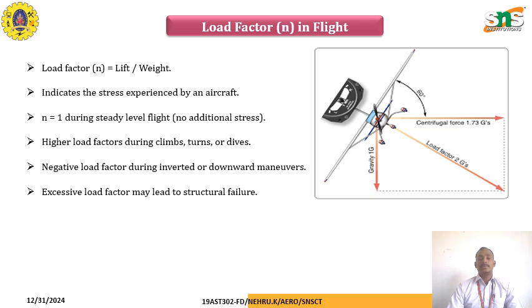It indicates the stress experienced by an aircraft, how much lift and how much structural weight is carried. n is 1 during steady level flight, with no additional stress acting on the aircraft. During climb, turn or dive conditions, it faces a very high load factor. In steady level flight, no additional stress is carried.